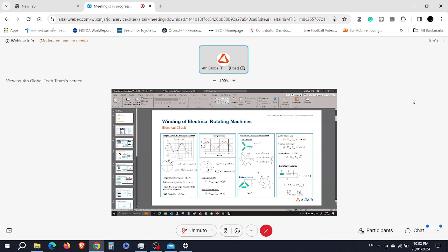So this is about the star connection, and the phase-to-phase voltage is linked to the phase-to-neutral voltage by a ratio of root square of 3. Then we have this delta connection. We still have this electrical angle between the currents, right? Here the phase-to-phase voltage is seen by two phases.